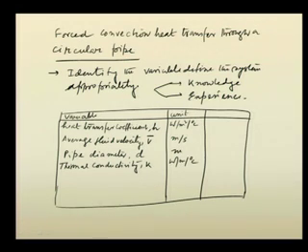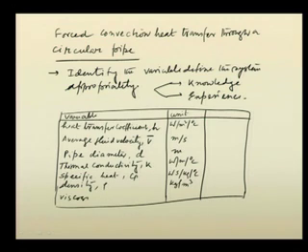Then we have specific heat, this is again a fluid property, Cp, this unit is watt second per kg per degree centigrade, and then we have density rho, and we know that it is kg per meter cube, and then we have viscosity mu, and it is kg per meter per second.